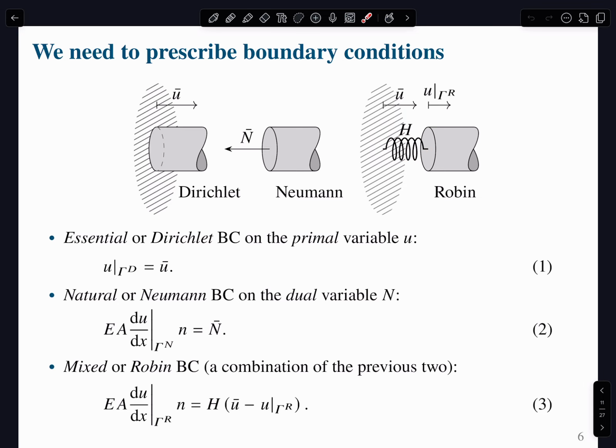And so now we want to prescribe some value of the displacement at Earth. So it's like my bar is not really attached to Earth, it's attached to Earth through a spring. And so depending on the stiffness of that spring, I'm going to get a different behavior. If that spring is extremely rigid, say infinitely rigid, obviously whatever U bar I apply to Earth is going to be immediately transferred to the bar.